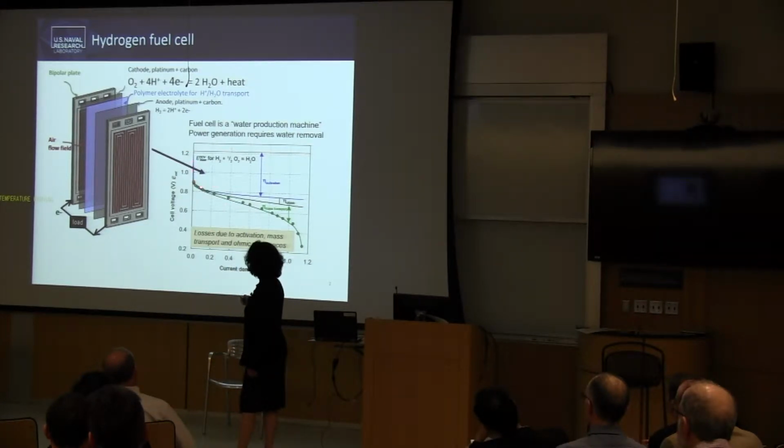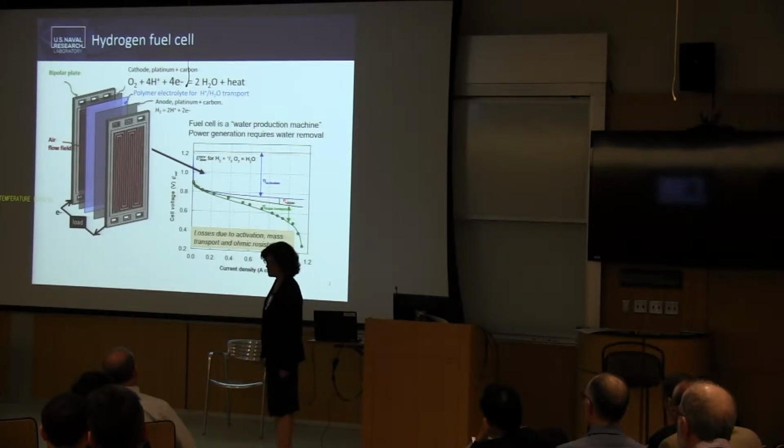So you're going to come down in voltage, and then it's not stiff like a battery curve, and it slopes like this. And there's three contributions to it. Activation, which is mainly oxygen reduction. Debbie talked about that. Ohmic, I can talk about that, but I'm not going to talk about that much today for the purpose of time. What I'm mainly going to talk about is mass transport.